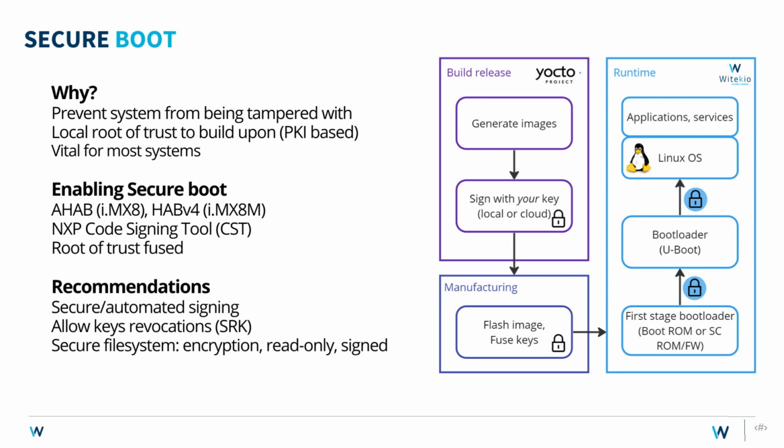Recommendation here, make sure that you have a way to revoke your keys. That could be through a system update, or through another way. If that first key, for example, were to be lost or stolen, you want to be able to revoke it. So you're going to have a fuse that you can break to disable these keys. You just have to have a way to revoke these keys.